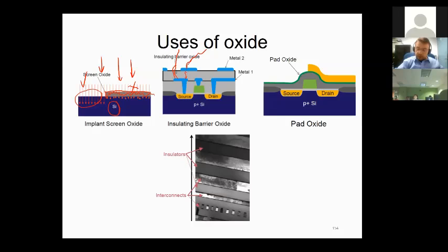Or we can try to smooth out the locations. You can see here, this pad oxide is a thin oxide. Its main purpose is to cover these kinds of areas to smooth out the whole trajectory for the upcoming layer, so that once you deposit the new layer, it will not see this kind of sharp change in terms of the topography. You see, this is really a huge slope here. It might break and create stress on the side walls, and that might put a lot of tension on that little thin layer there.